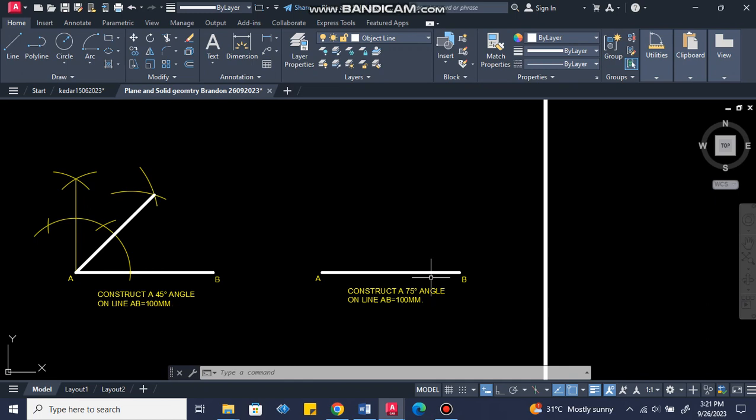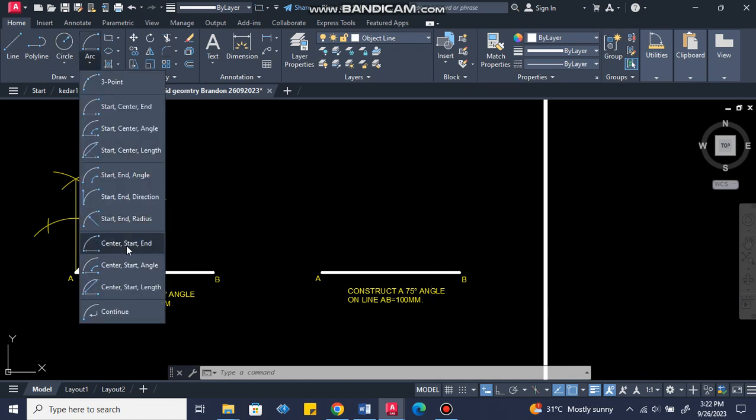We know a 60-degree angle and a 15-degree angle would give us a 75-degree angle. Getting the 60 is straightforward, and in order to get the 15-degree angle, we need to construct the 90 and bisect that. Okay, so let's take a look at it.